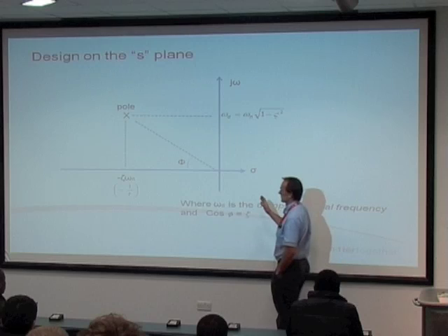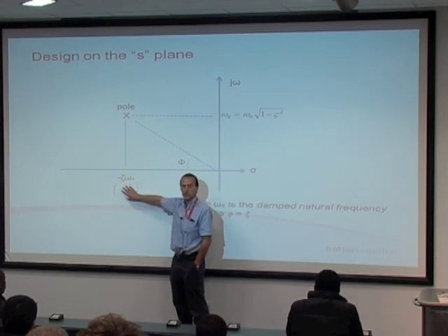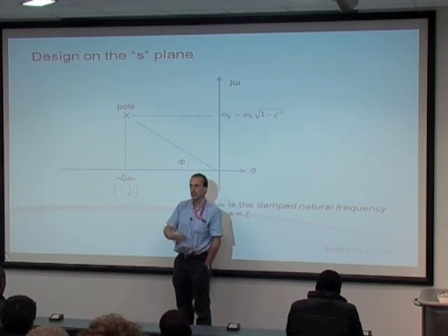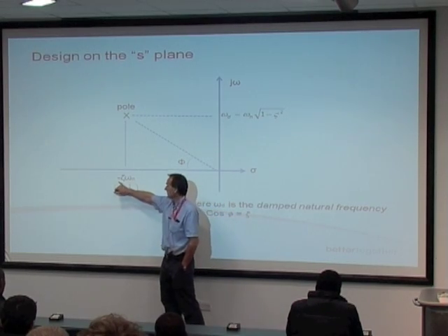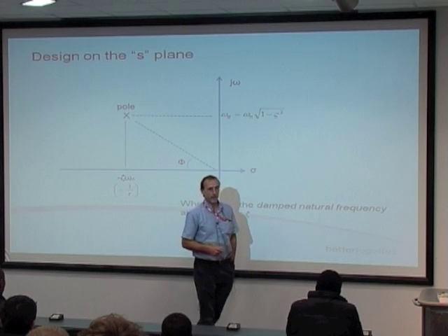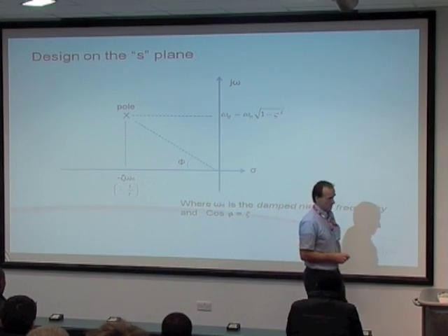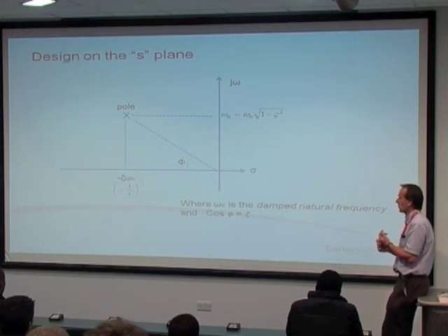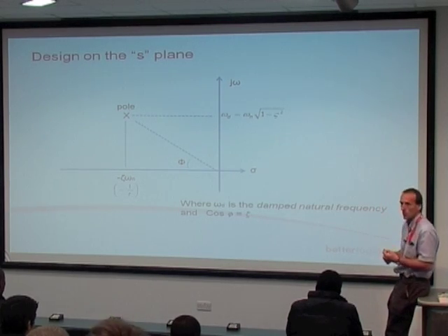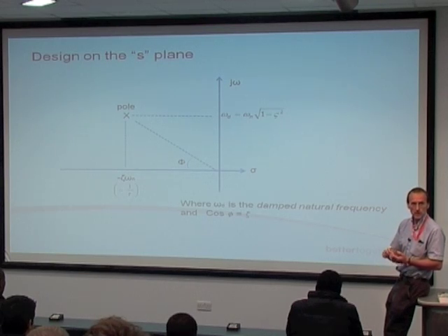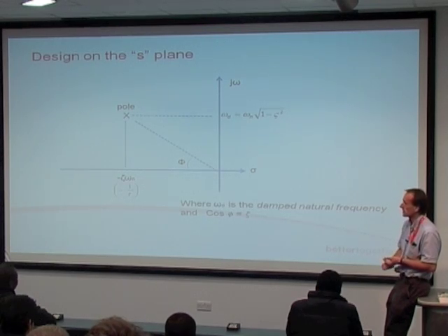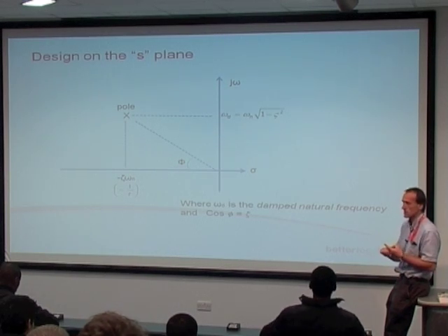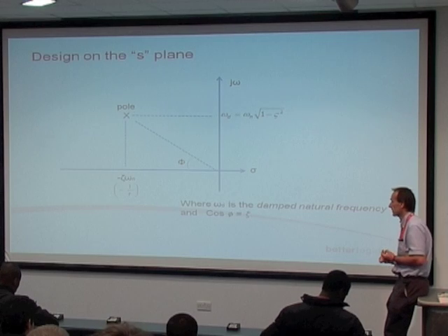The real part, we've looked at it for first order systems, is minus 1 upon the time constant. Relating it to second order systems, it is minus zeta times omega n. Okay. So we can immediately go from omega n and tau into pole positions and place our pole that way. There are some other things we can relate it to.